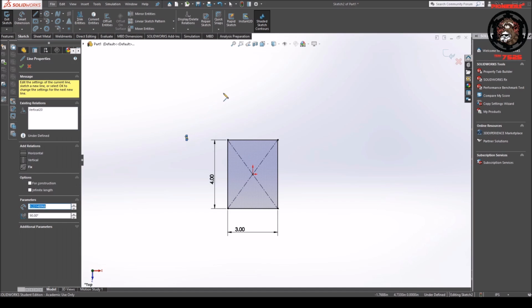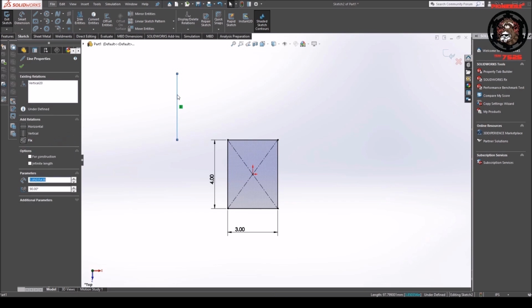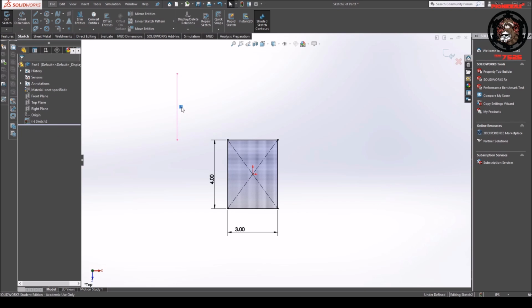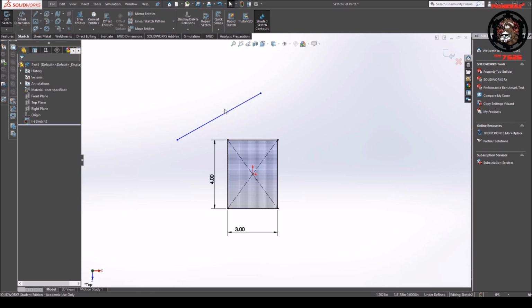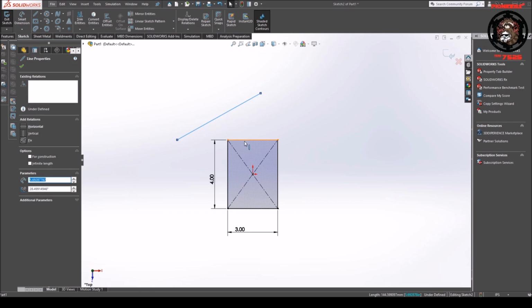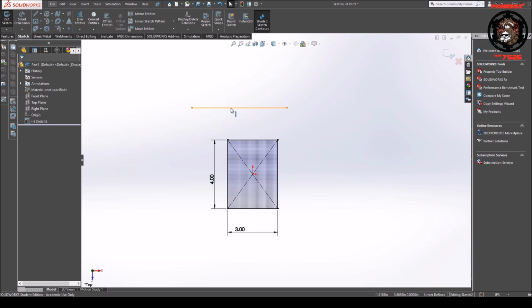And for example, say I have a line like this. Oh, you can see that it automatically made it vertical, so we're going to have to just delete that. So now that we can angle it, and say I want this parallel, same thing, if you hold shift and click these two lines, we have options here. We can do a collinear, which will make this linear to it, but I just want to make it parallel, so we're just going to do parallel like that. And we can move it.